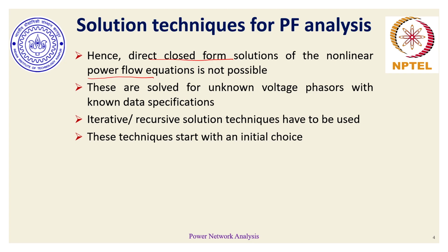And these power flow equations have to be solved for unknown voltage phasors with known data specifications such as network parameters, network topology, both of which are obtained from the parameter estimation exercise, which is part of state estimation, load and generation injections, tap positions, capacitors, etc. So all that input information is known, which again we have discussed in the basis or assumptions involved in power flow.